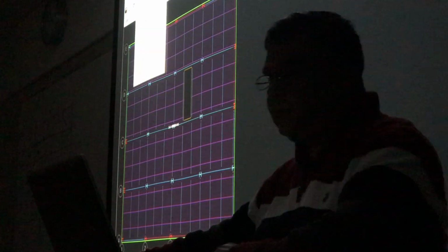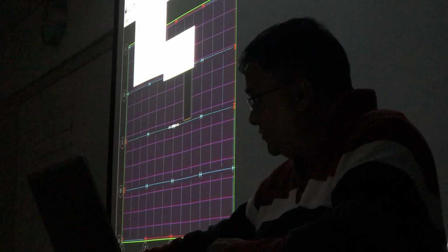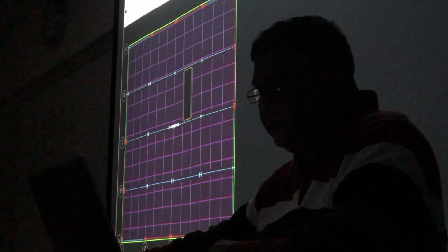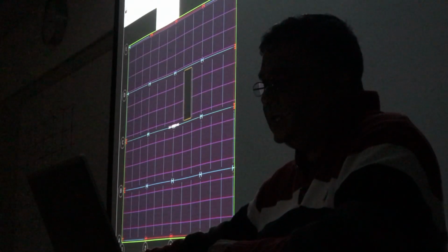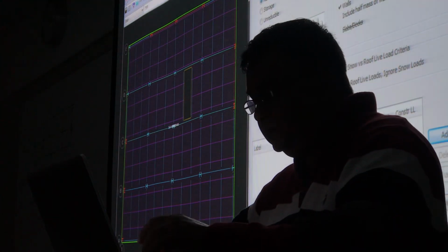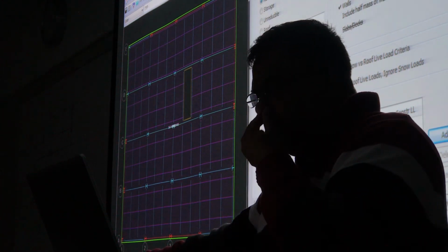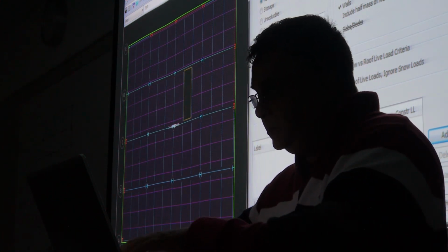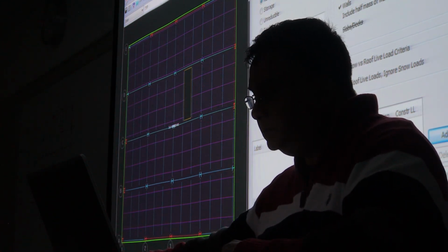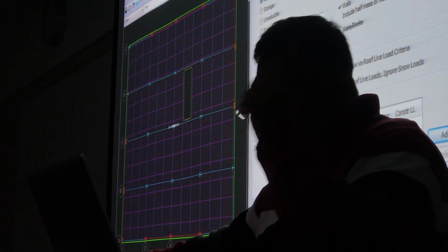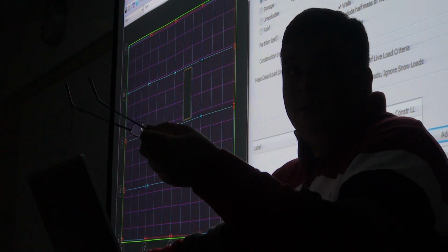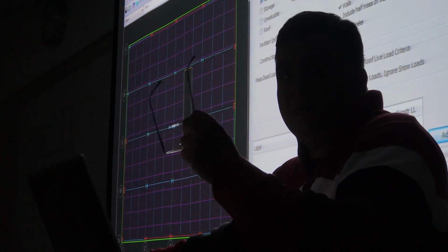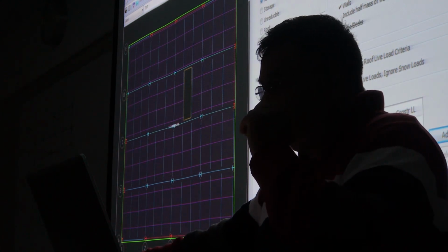Now what is next? Loads. That means I have to find out loading. Okay. So the loading is not there, so I have to go back to the property table and define some load. First thing that I will do is the surface loading, PSF loading. And I'm going to say that dead load is what? 75 PSF. Okay. Remember, I showed you 60 PSF for the deck load, plus another 15, right? Additional floor finish and so on. So 15 PSF.